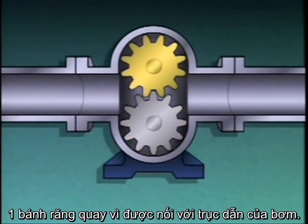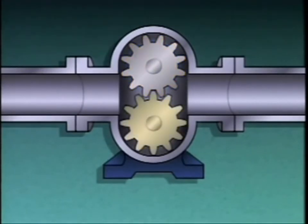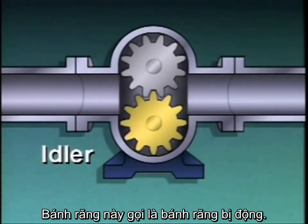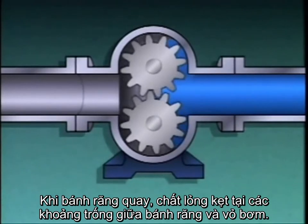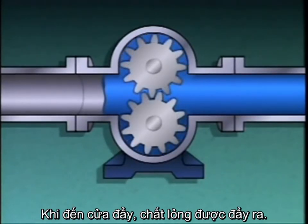One gear is rotated by the pump's driver. This gear is often referred to as a power or driver gear. The other gear moves because its teeth are meshed with the teeth of the driver gear. It's called the idler gear. During operation, liquid enters the pump through the suction port. As the gears turn, the liquid is trapped in the spaces between the casing and the gear teeth and moved along the casing. When it reaches the discharge port, it's forced out of the pump.